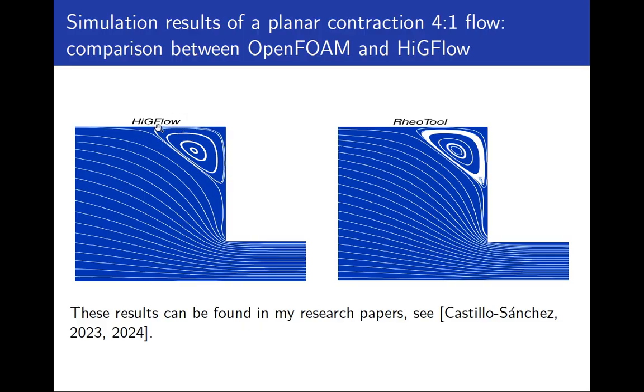As I said before, HighGFlow is the CFD software I was working with that uses the finite-difference method to solve the governing equations, and Rheotool, which is based on OpenFOAM, uses the finite-volume method. We compare the streamlines from both CFD software, and you can see that they predict roughly the same behavior. The size of the vortex obtained from HighGFlow is basically the same as the one obtained in Rheotool. And these results can be found in my research papers that were published in 2023 and 2024.